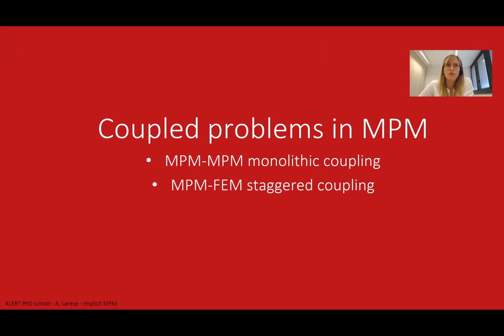We decided to go for penalty method using boundary particles, to minimize the diffusion of the information that we want to pass from the particles to the nodes, and the other way around. Because this problem of unfitted methods is very common in coupled problems. In fact, in coupled problems, the interface between the two materials that you're considering is moving and deforming according to your problem.